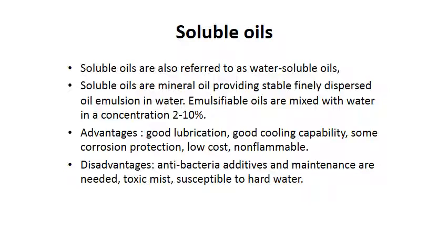The main advantages of soluble oils: good lubrication, good cooling capability, some corrosion protection, low cost, and non-flammable. The disadvantages or drawbacks of soluble oil: antibacterial additives and maintenance are needed, and it is toxic.